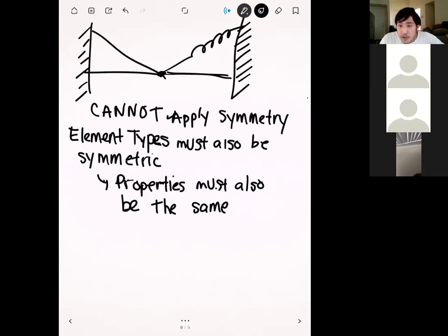All right, so the question is, but then it can move in the X direction too. Can we use the roller? You know, it can move in the X direction if we have this spring here, but because of the loading, it's only going to displace in the Y direction. So in that case, even if we have springs over here, you would still do a roller type.